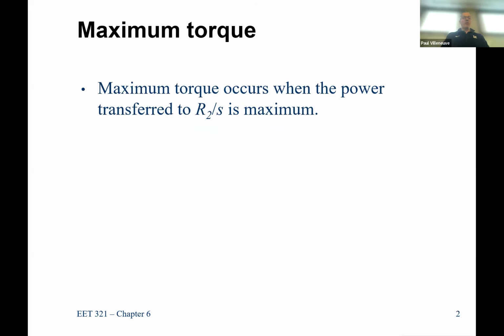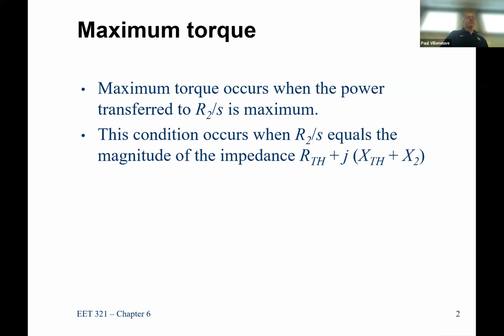All right, max torque. We already talked about max power transfer, the last class we were actually in person. So max torque occurs when the power transferred to that R2 over S is at a maximum. Remember that rotor circuit? That's the max power.